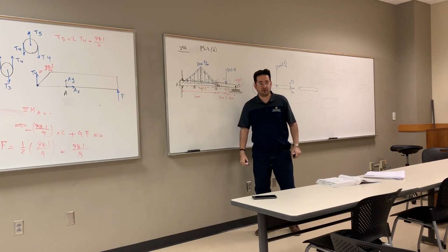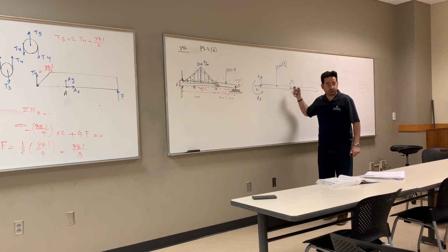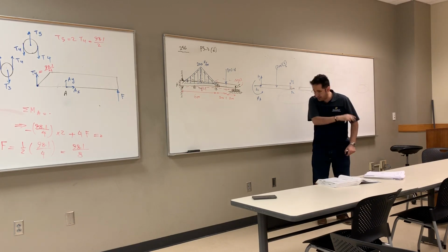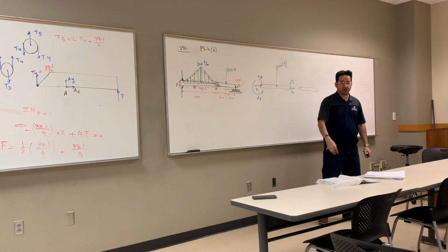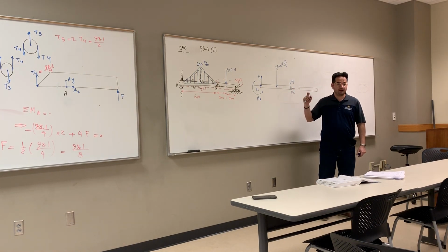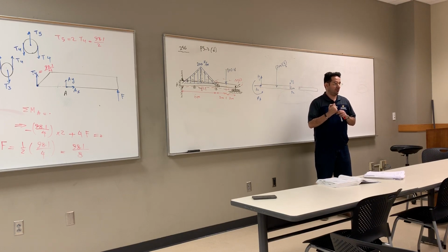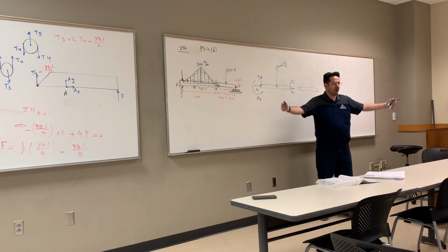Look, in the test, I don't want you guys to put a moment there. If I see a moment there, I immediately just cross it out. I don't even grade it. This is the most terrible mistake. That means that you didn't study even the basic intuitions, like frictionless pin. Well, I don't have a moment there, and nothing comes from the outside force.